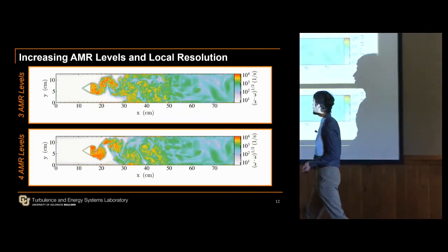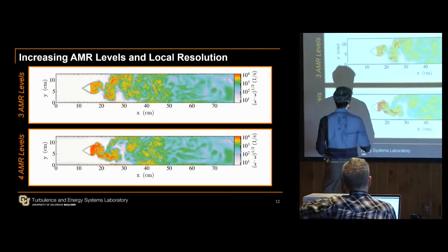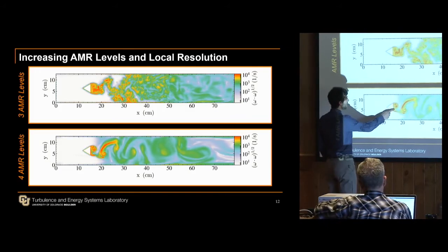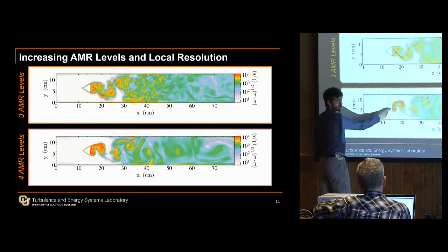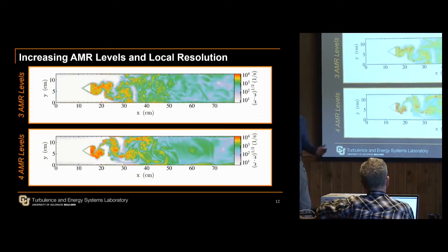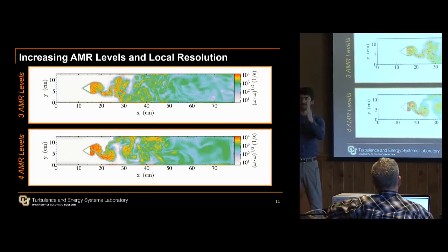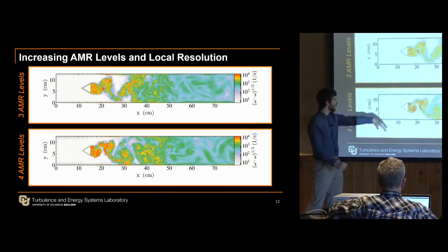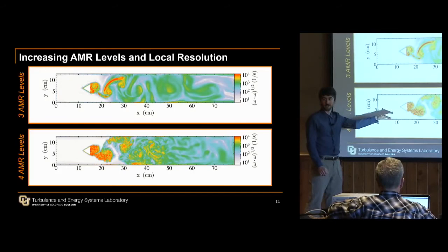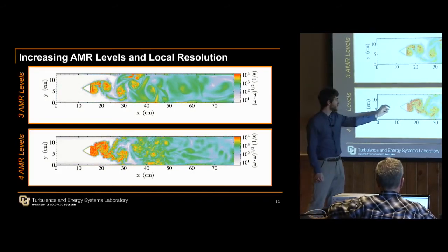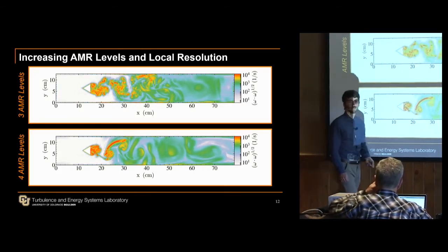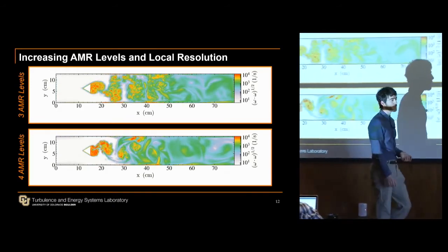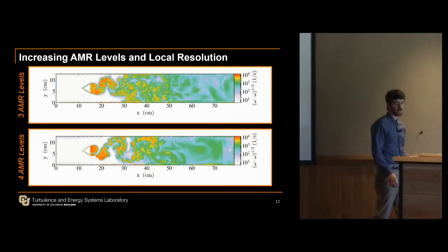You can see in these simulations, we have very intense vorticity penetrating the recirculation zone region and a reduction in size of that region as well. So overall, the vertical flapping motion here changes those recirculation zone dynamics, which we actually care so much about for the stabilization of our flame.